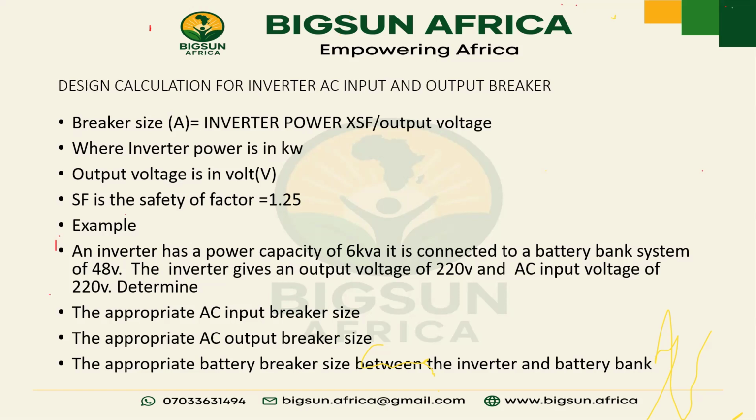So you expect that the client is not going to put anything above 5 kVA. But the best option is for you to use this formula. Divide it with the voltage of the inverter so that at any point the person doesn't have to pull anything above what he's supposed to pull from the inverter, so the inverter doesn't have to make noise, or complain of any high voltage or overload.